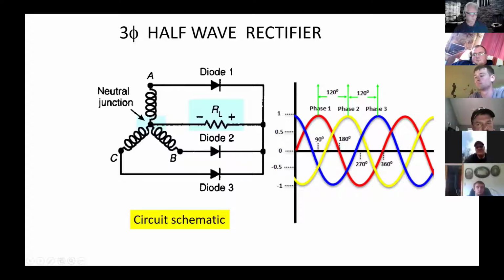So you'll have 3 waves, 3 windings, basically 3 secondaries. And if I have 3-phase power coming in, I'm going to rectify all 3. This is pretty much like the alternator on your car. Your alternator usually produces 3-phase power, and you're going to have the rectifier that's in it and a voltage regulator.